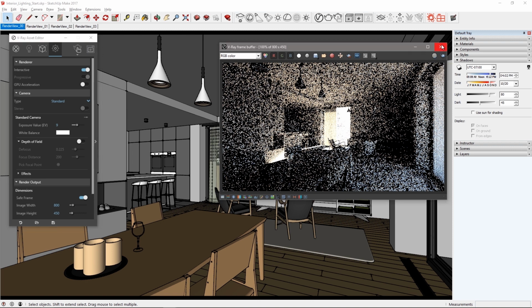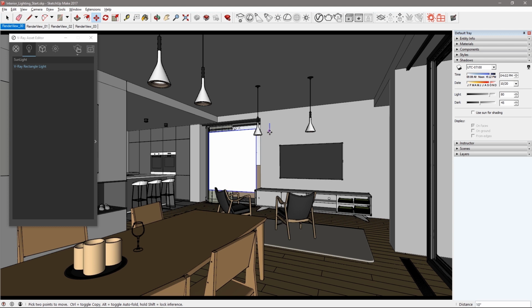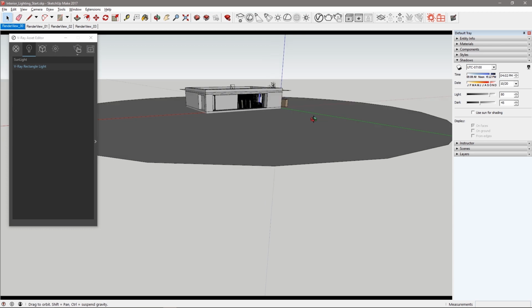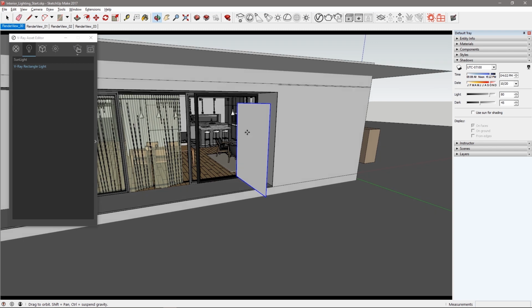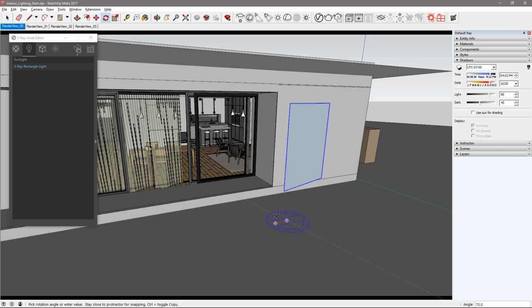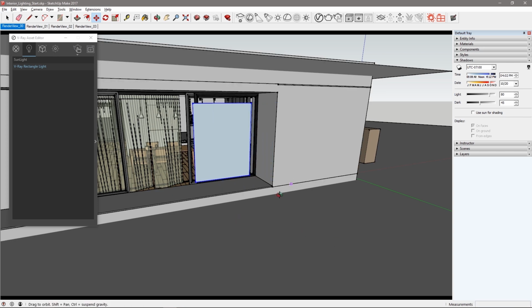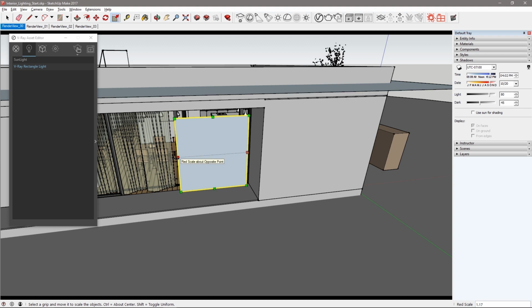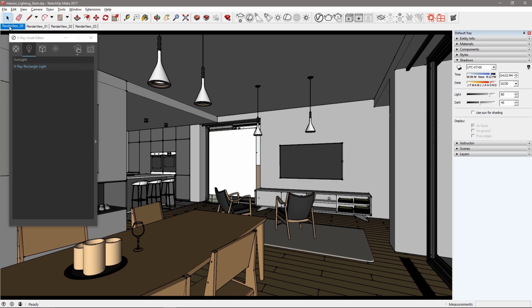I'm going to create some additional light in the scene. Click to create a plane light and place it and scale it like so in front of the window. Now go ahead and copy this light and then place it outside of this sliding glass door, sizing it roughly to the door's scale. This exterior light will send light through the glass door into the room, while the other one inside will soon make into a portal light to facilitate the existing sunlight to come through from the outside environment. Set the view to Render View 00 and kick off an interactive render.